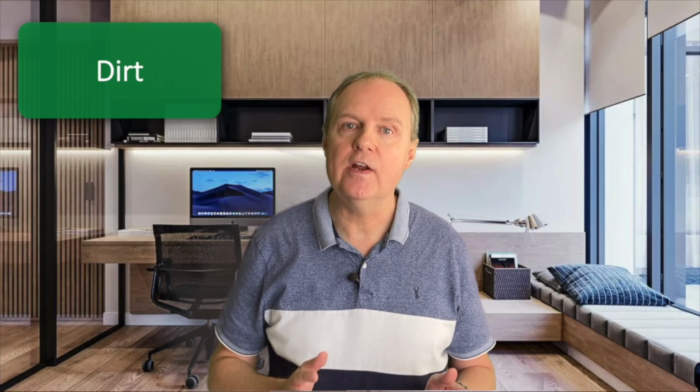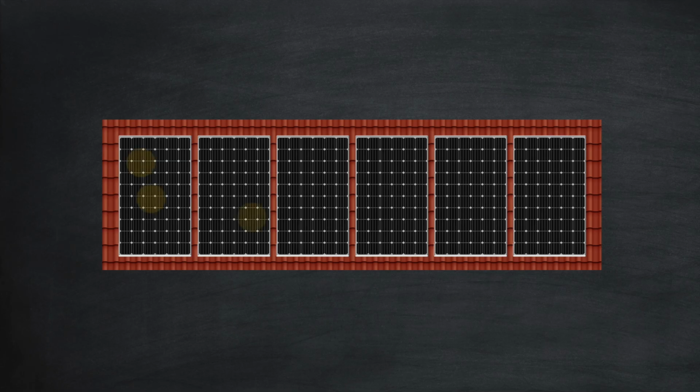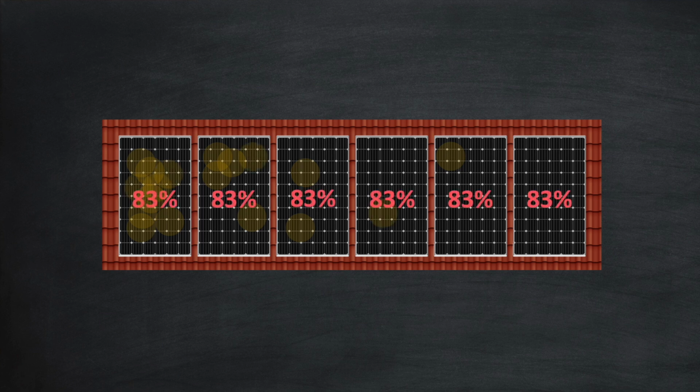It is inevitable that over time your solar panels will become dirty, and if dirt builds up more rapidly on one section of your array, let's say because of a nearby tree or birds roosting on the ridgeline, and you don't have any optimizers or microinverters, this can then bring down the production to the dirtiest panel in your array. You may want to take steps to have your panels cleaned every now and again to avoid such problems, and of course the reduced power generation.